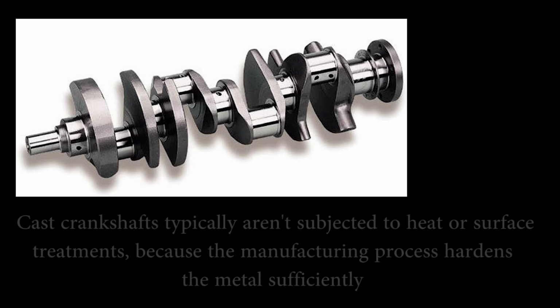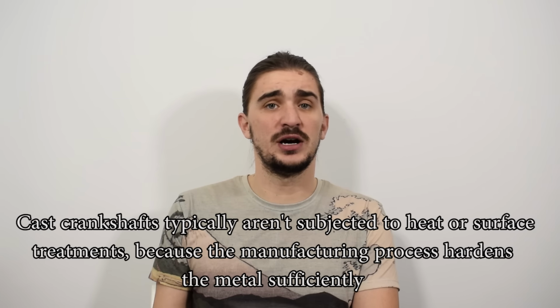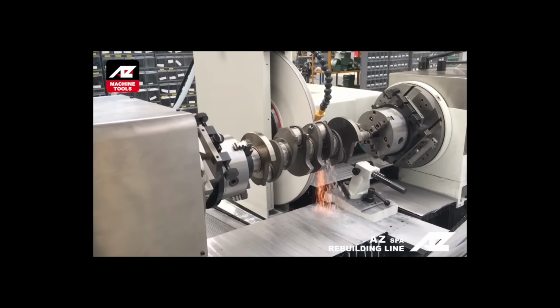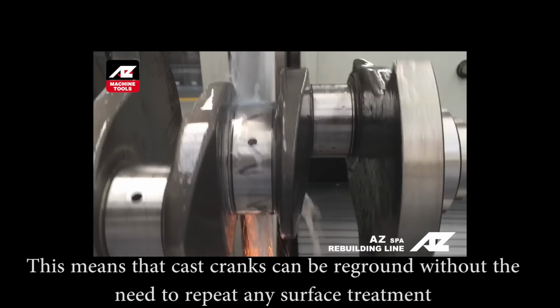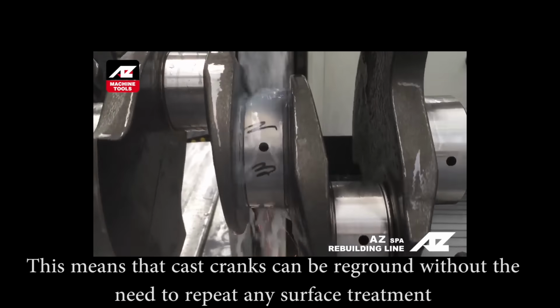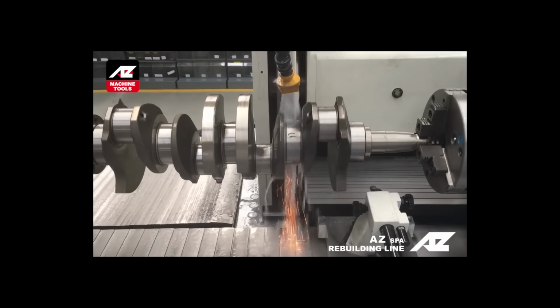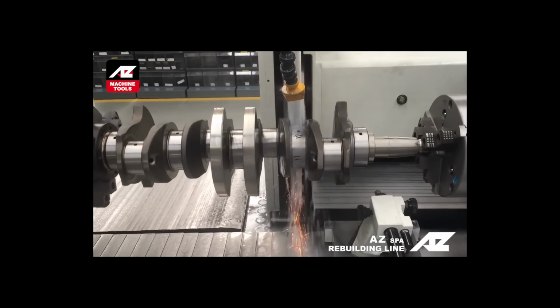Now, modern cast crankshafts typically don't undergo heat and surface treatments. The manufacturing and subsequent machining process hardens the metal sufficiently, so there's no need for additional treatments. And this is good because it usually means that cast crankshafts can be remachined or reground without any need for repeated heat or surface treatments. On the other hand, forged crankshafts usually start out by being softer than cast crankshafts, and they do require heat or surface treatments.